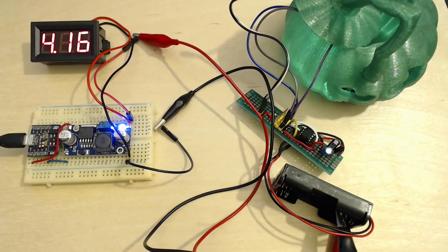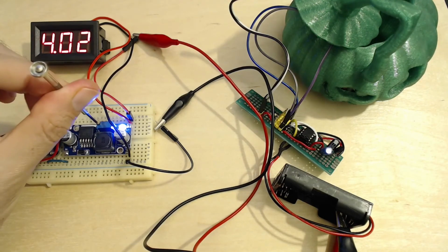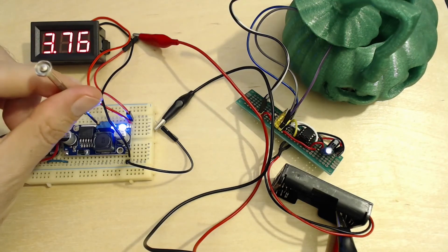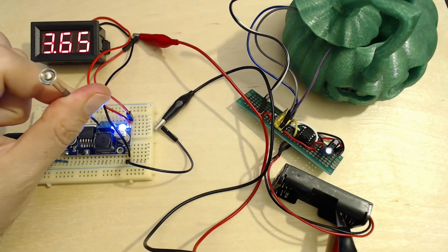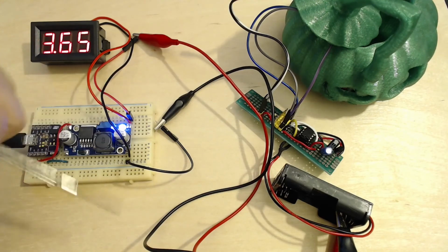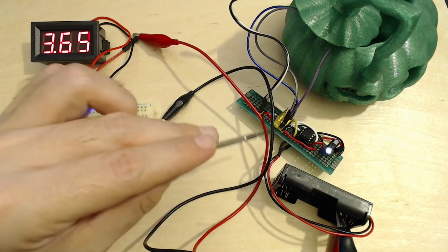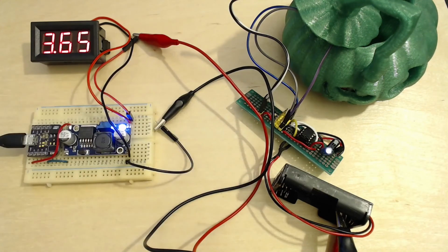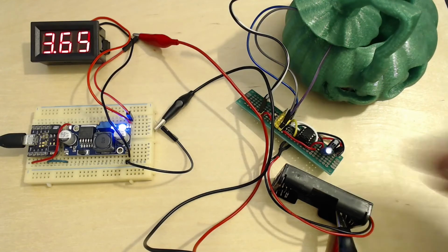So what we are going to do now to simulate this low battery situation, we will just drop the power supply voltage to, let's start with 3.6 volts first. I imagine everything will be fine in 3.6 volts because the maximum dropout on our regulator is 0.3 volts. So that should give our micro a good 3.3 volts to work with. Everything should be fine. Yeah, it looks pretty good.